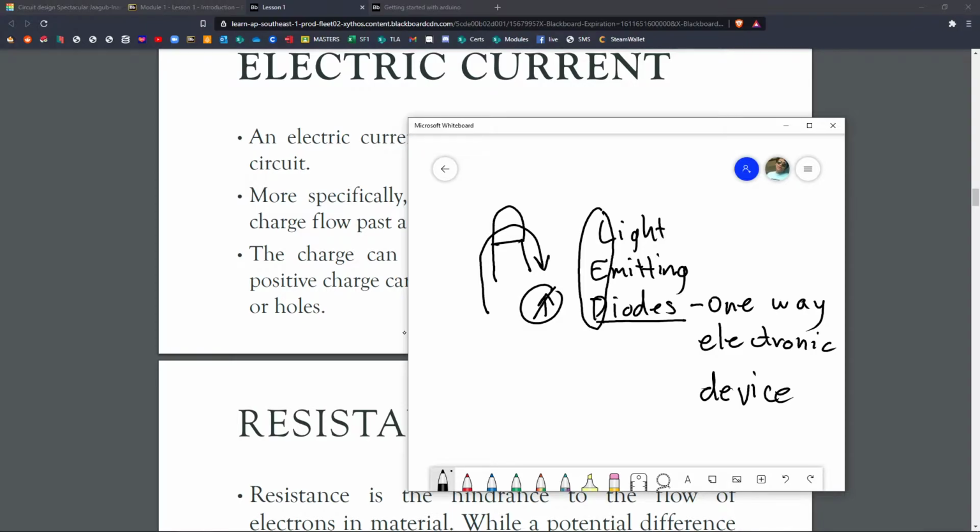If we push a lot of electricity to it, for example, if we use 5 volts raw in an LED lamp, because most of the Arduino pins usually output as much as 5 volts, the LED will automatically pop, meaning you destroyed your light emitting diode immediately, which was the case during our lessons last year.